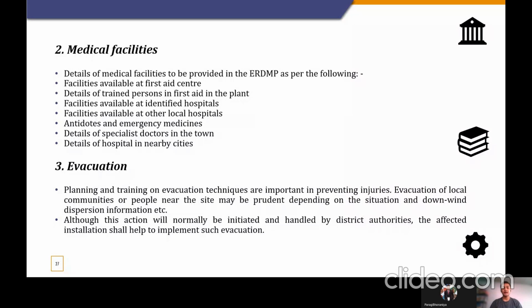There are gathering points, or assembly points, defined in the facility. And there are sirens and codes given by organizations such as PNGRB that should be followed, such as the magenta alarm, different siren codes and different types of beeps. Each carries a particular message to the professionals, such as evacuate from this point.